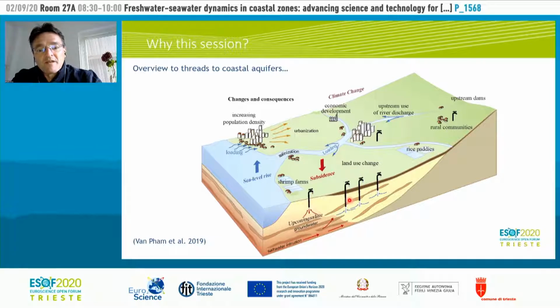So if we tap enough water from the near coast groundwater aquifers, and at the same time we have sea level rise, then saline groundwater can intrude into the existing aquifers and deteriorate the quality of these, and maybe even making them unusable for any type of future activity.